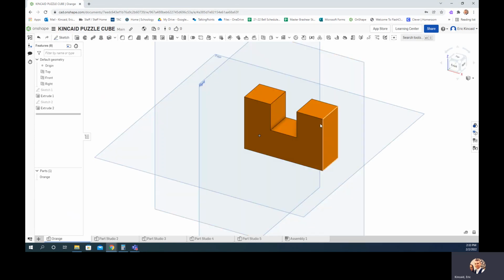and I'm going to create this same exact part. Looking at this part, I know that it is 3 blocks wide, 2 blocks tall, and 1 block in depth. So we want to remember our dimensions as each block is a 0.75 or 3/4 inch cube. That means that anytime there's 3 of those blocks across, it is 2.25. And anytime that it's 2 blocks in length or height, it is 1.5. And then finally 1 block, this depth will be 0.75.